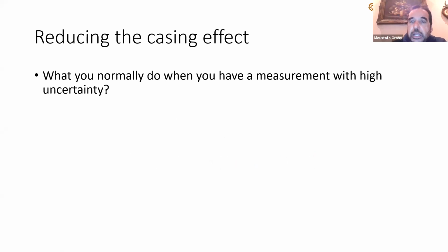This is one thing, and also to have either a stationary measurement. You stay there for quite some time to really gather good information, or to repeat the measurement. Whenever we have a measurement that's very low, that's what we really do, even in the lab. You repeat the measurement more than once, okay? And you try to stay there as long as you can to give enough time to build a good signal to noise ratio, okay?